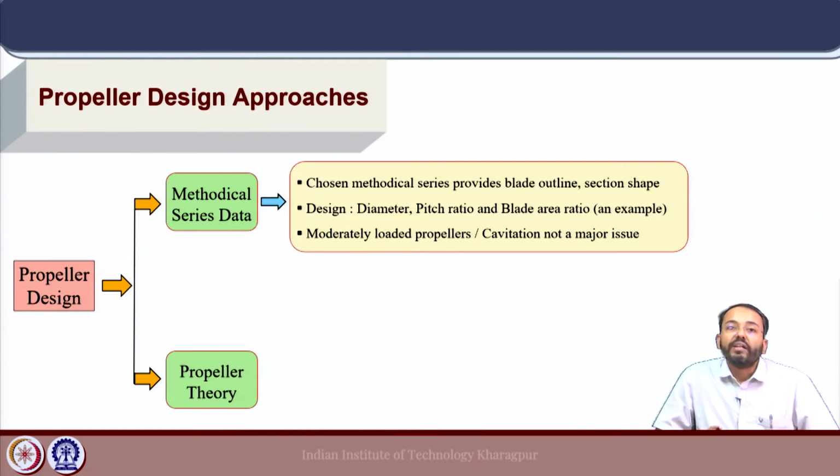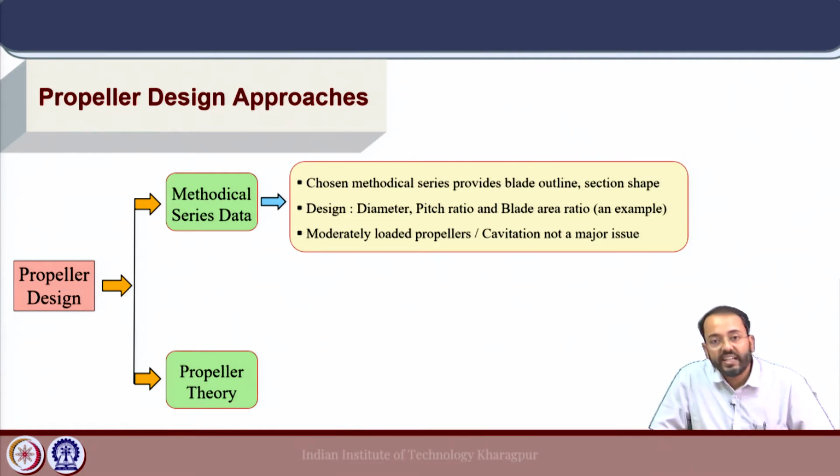Okay. Now, these methodical series data are used to design propellers which are moderately loaded and where cavitation is not a major issue. So, the series data are extensively used for propeller design, and even for cases where one uses propeller theory to develop detailed design, even in those cases a first hand design using a standard methodical series data is obtained to have a basic idea of the design parameters.